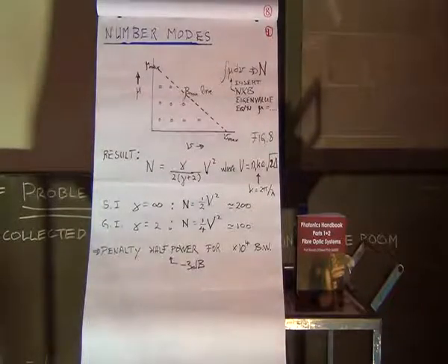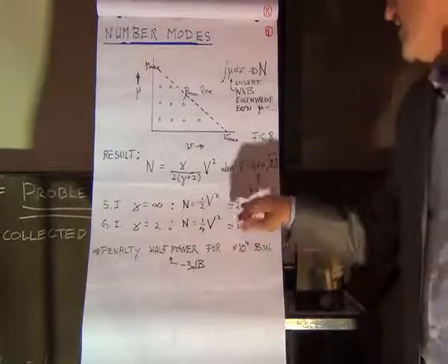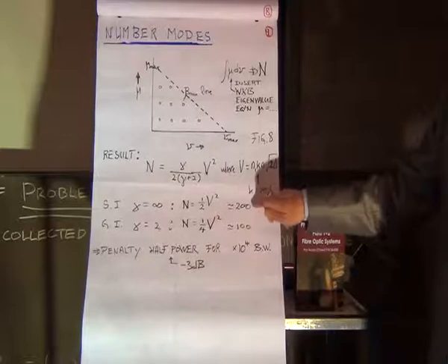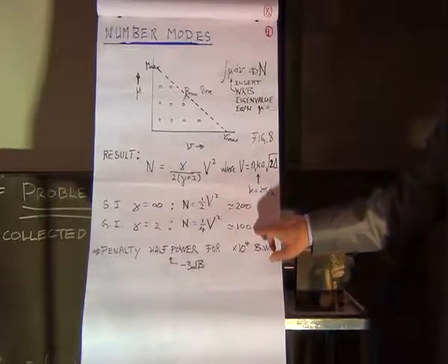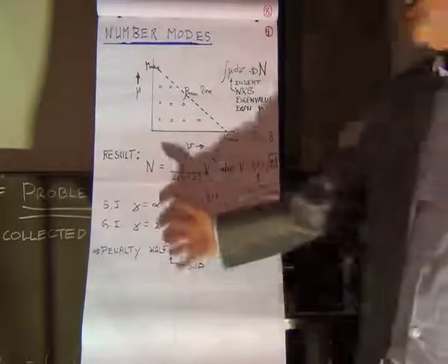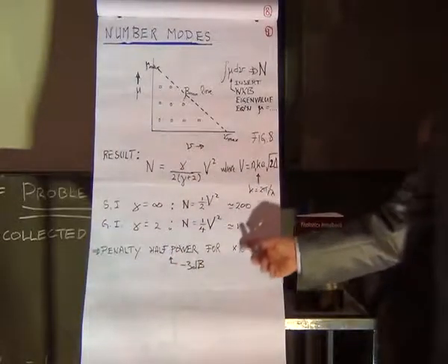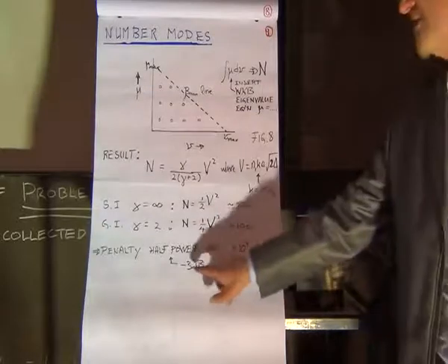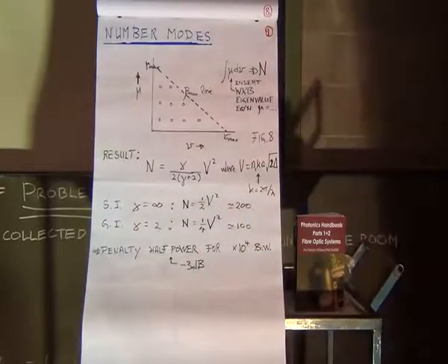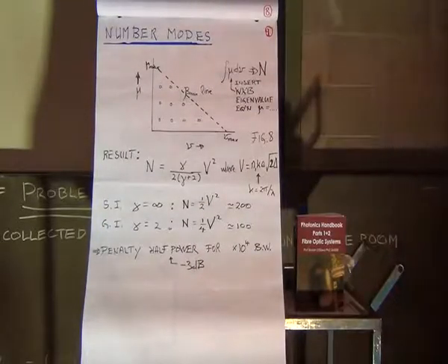They're all equally valid solutions to the wave equation. That means there's twice as much power in this fibre as in the graded index. So our improvement in bandwidth of 10 to 100,000, what it's costing us is half power, 3 decibels in our loss budget. Well worth it.